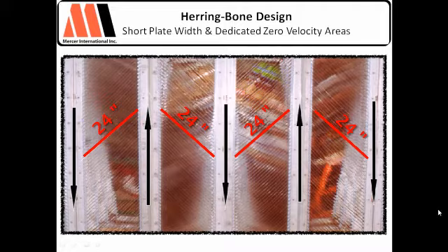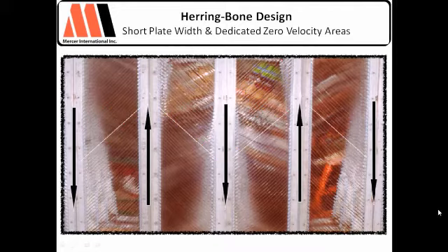So as you're looking throughout industry and you're comparing and contrasting and considering designs, look for a plate pack system with short plate widths. The short plate widths are very important. It also gives you a tighter rise to run ratio, and that's important for solids.